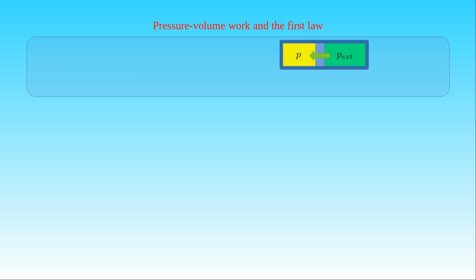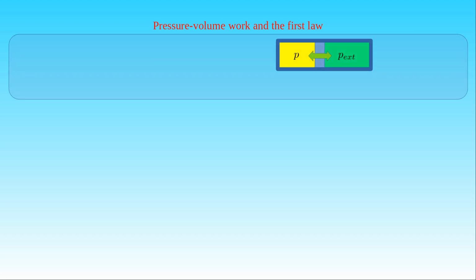We have seen that the pressure volume work done on a thermodynamic system by external pressure forces can be approximated with the product of the external pressure and the change of the volume of the system, provided its boundary is a rectangular cuboid in shape. We can also show that the pressure volume work has the same expression in the case of the compression of an ideal gas in a cylinder by a moving piston. However, in order to make the role of the external pressure more transparent, we will use a moving wall inside a closed cylinder instead of a cylinder with a piston.